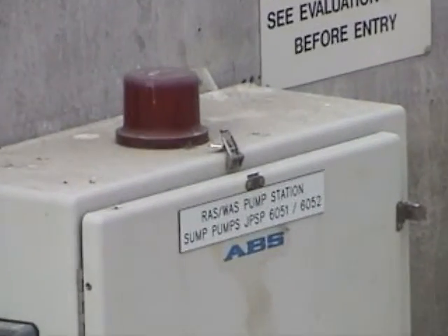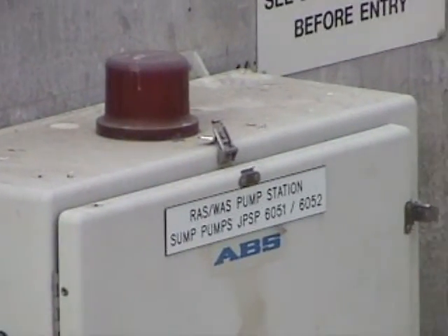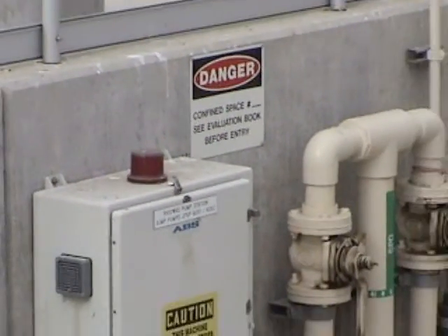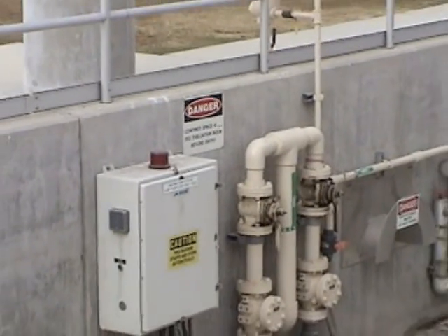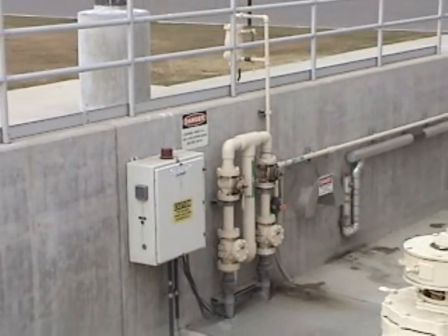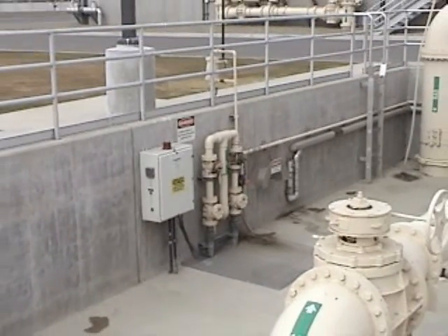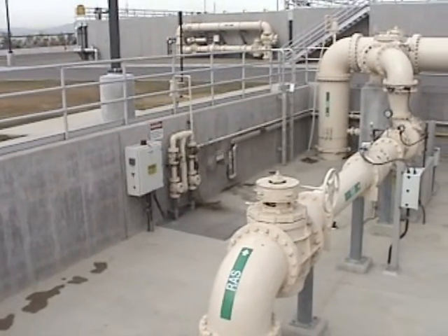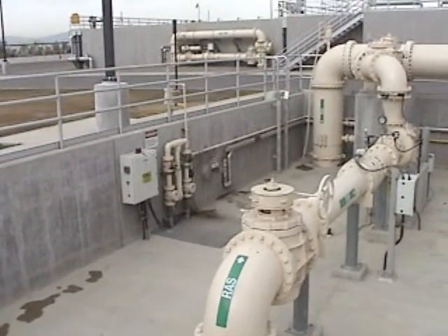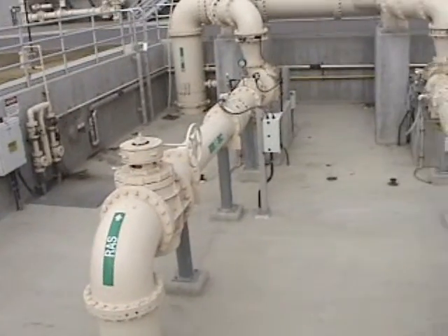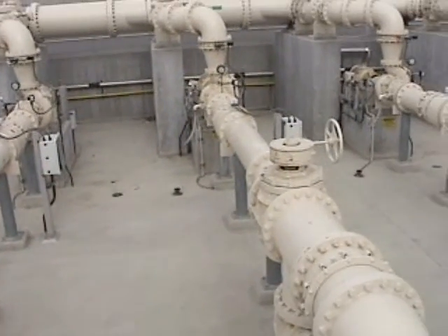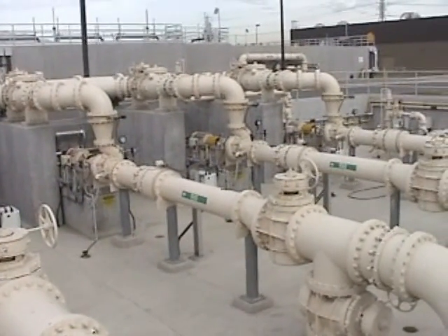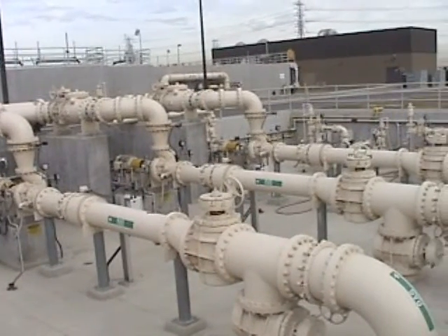And if it's after hours, it's also going to send a priority 1 alarm out to one of our pagers. It's really important to respond to those, because if you get a high level in that sump, it may be just a hose running, or it could be the station flooding out. Maybe we've broken a pipe or something like that. So it's really important to follow up on a high sump alarm. And throughout the day or on your rounds, you'd want to check to make sure those pumps are pumping.